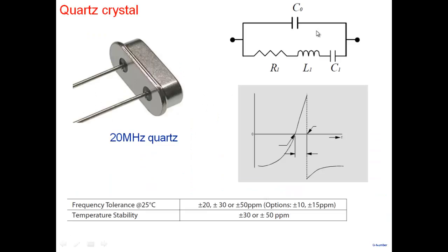A little bit about this quartz crystal, for example. What is so interesting about quartz crystal? So you can buy these. They come in, depending on the size and the geometry, you get 3 megahertz, 6 megahertz, different kinds of quartz crystal, 20 megahertz here. So when you look at quartz, it can be modeled in terms of this here, in terms of a equivalent circuit that you see here, R, L, C, and C naught here.